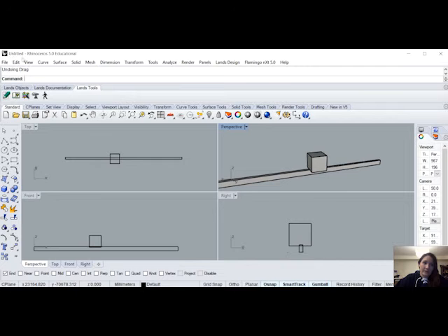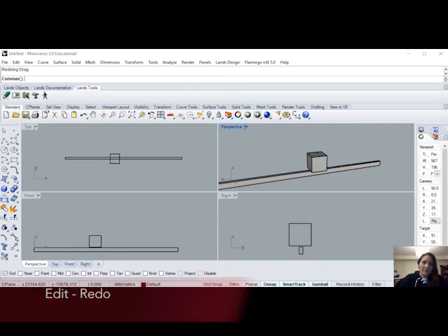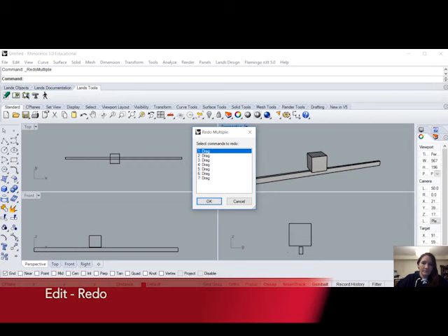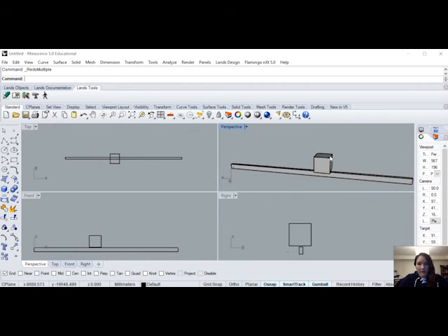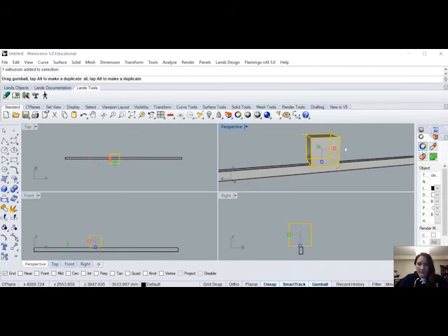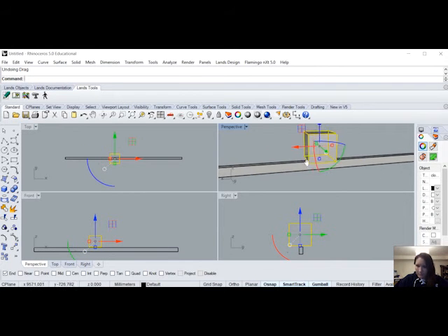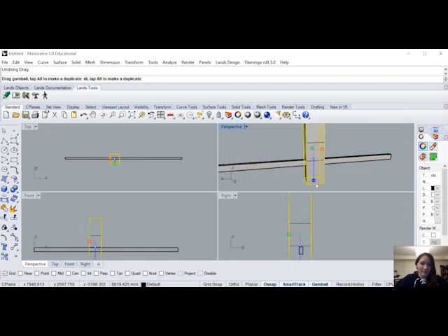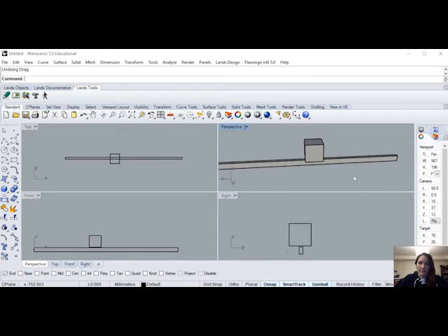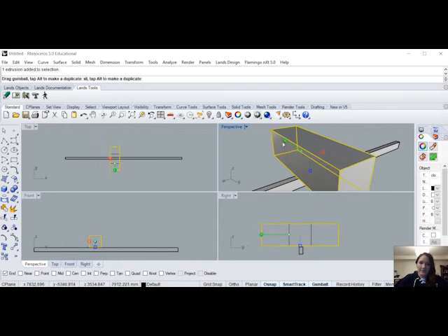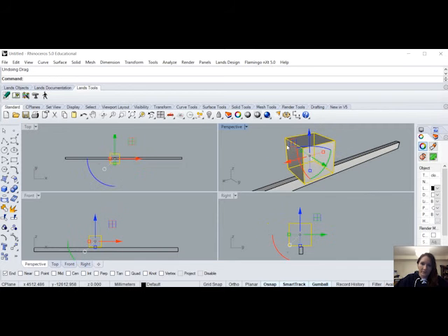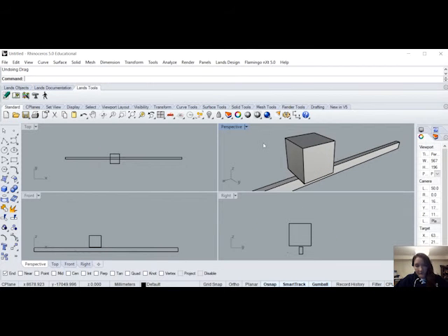If you ever need to redo anything, you can go up here to Edit, and then you can just redo. And you can redo multiple if you want to. Okay, so Gumball widen, and then you're like, oof, no, I liked it better as a square. But wait, what if I wanted it taller? That's the blue, up and down. Taller or shorter. Let's not be too picky here, whatever you want. And then obviously green, same kind of situation is going to happen. Control Z that to get it back. Control and Z. I press Control first and then Z, because if you press something else, it comes up at this top, and it's not nap time yet.